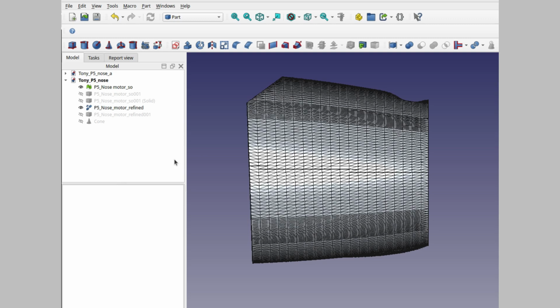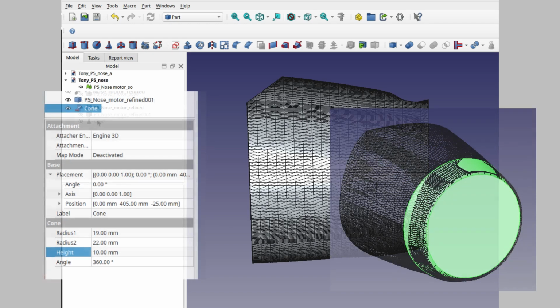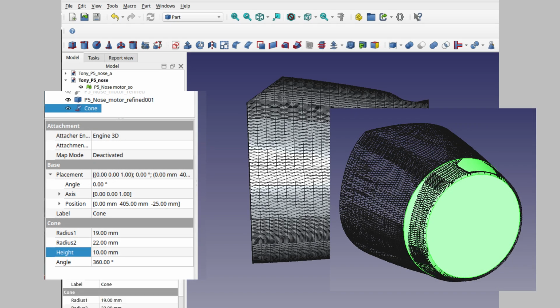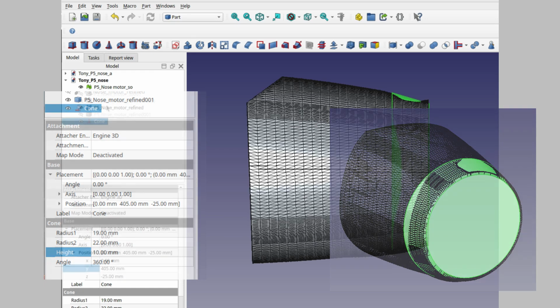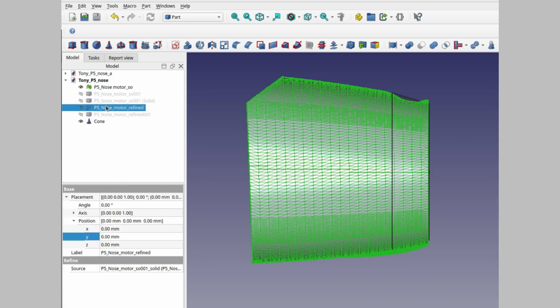Now, there's a question about accuracy. Doing a sketch with a revolve might get me something kind of like a cone to work with, but really I don't want the hassle of all the trig. Using the inbuilt cone primitive, I could be precise without a lot of maths. 10 millimeters seemed to be a reasonable distance to blend. As we shall see later, well, there was a bit I missed.